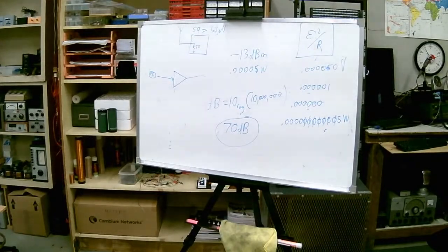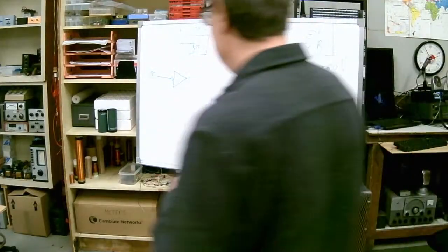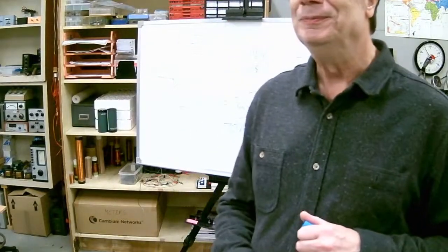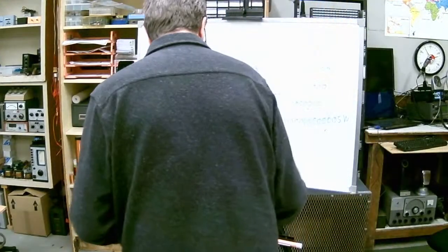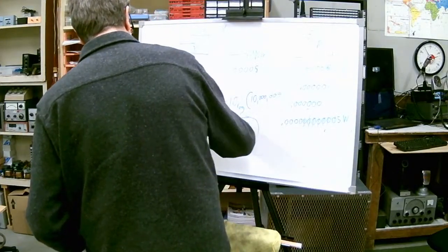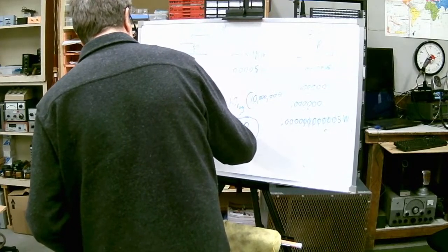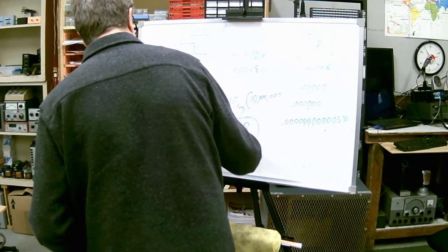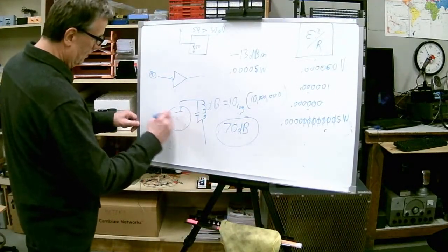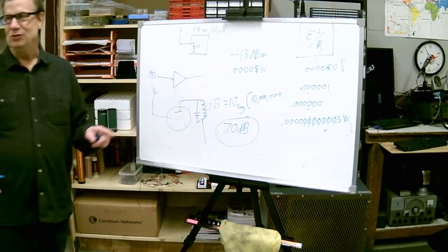The way that works is it's an oscillator just on the verge of oscillation. We were talking about amplification, how a tube amplifies. They did it in one stage. They had a tuned circuit out here, and you had your antenna connected here, and whatever the grid does is your input signal.